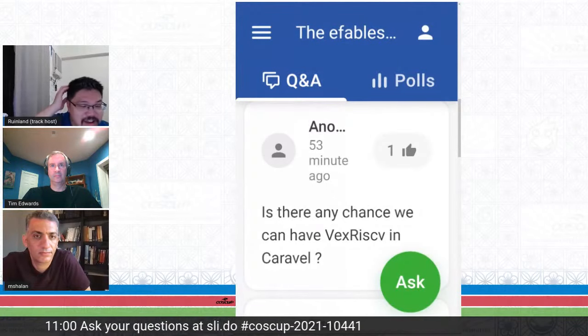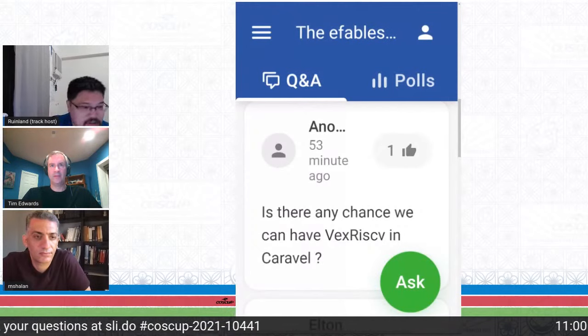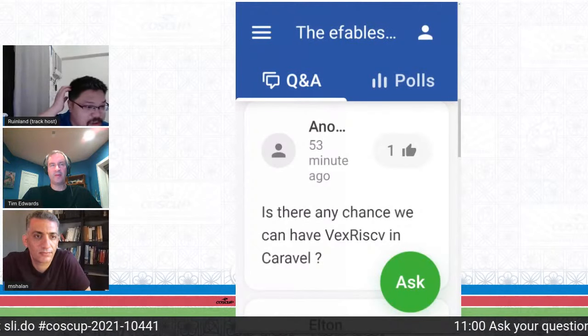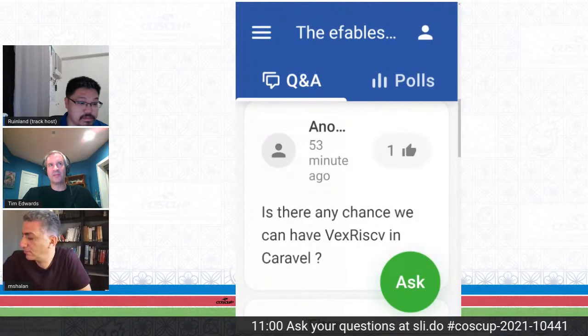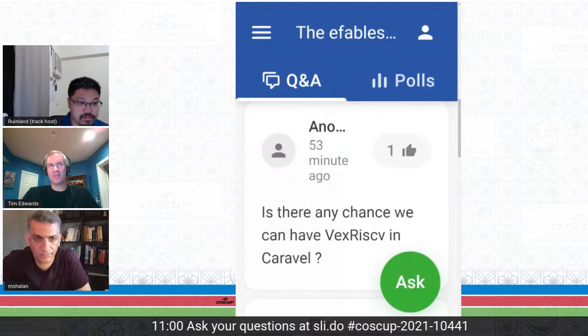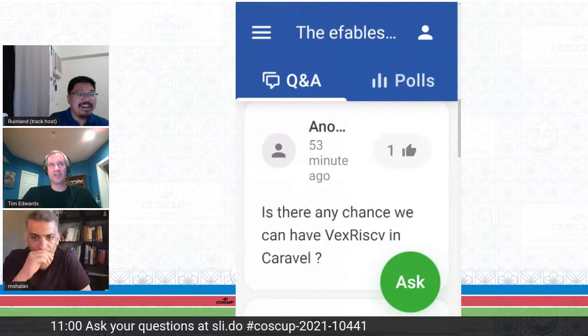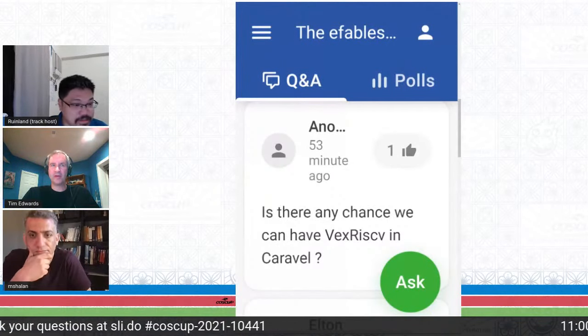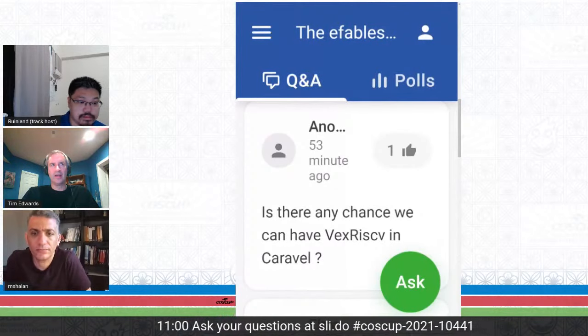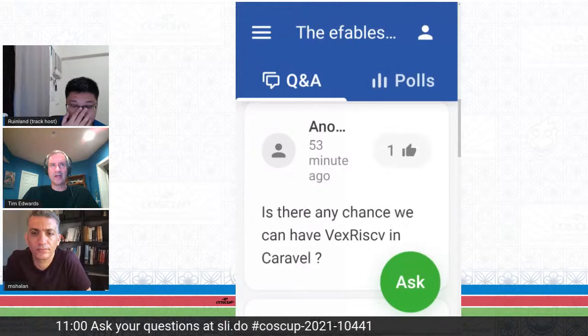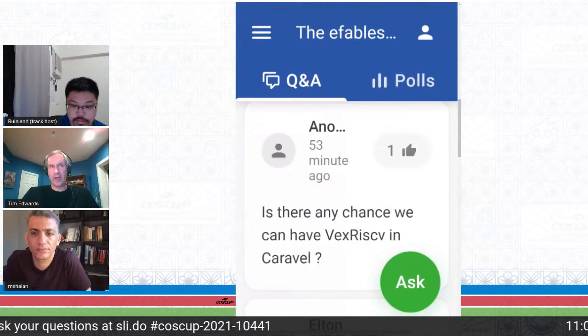Yeah, the answer is that if you're looking for something that you would be able to put Linux on, probably not. Just given the fact that this is a 130 nanometer process and you've got 10 millimeter squared of space, you can do small microcontrollers. Doing something that would support an entire operating system like Linux, probably not.